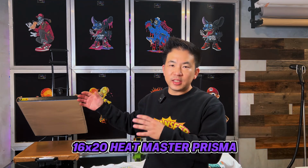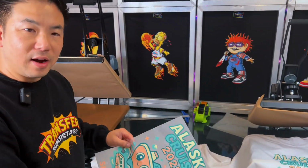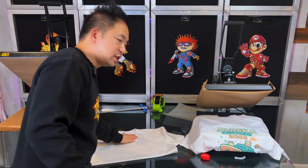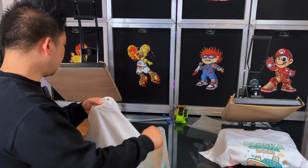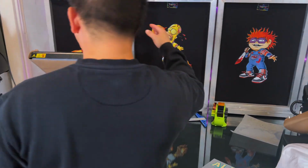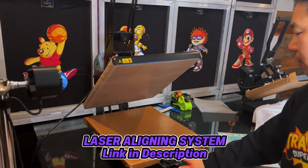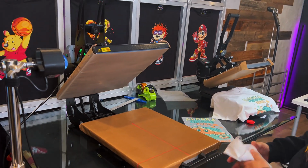Now that we've pressed on a t-shirt using the 15 by 15 inch heat press, let's compare it to the 16 by 20 Heatmaster Prisma. So again, we have our transfer, our t-shirt, the Smart Blanks 100% cotton. We have the Heatmaster Prisma. I've already preheated it to 300 degrees. Have our laser set up. It's a pull out, so it's a lot easier to align.